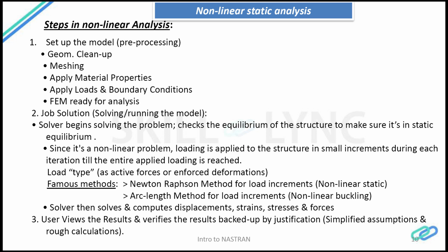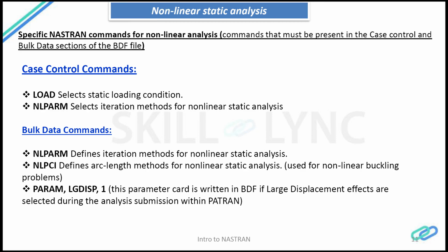So now we'll move into the parameters that are required for running a nonlinear analysis. For any nonlinear analysis, first we need the static load condition. That should be mentioned in the case control section of the BDF file. We need the load command, and finally there is an NLPARAM command, which is the nonlinear parameter command, that will select the iteration method.